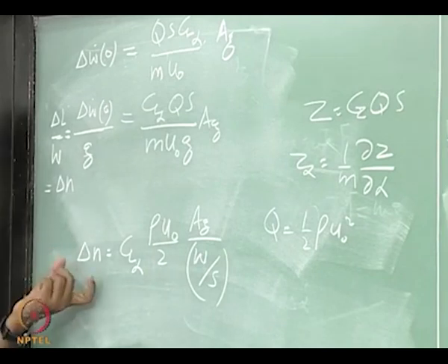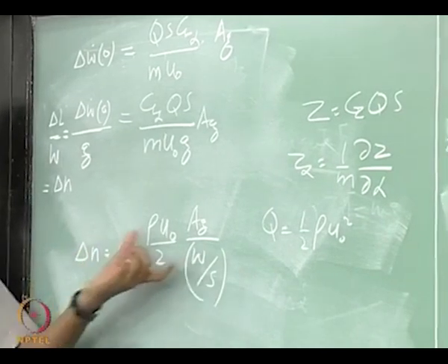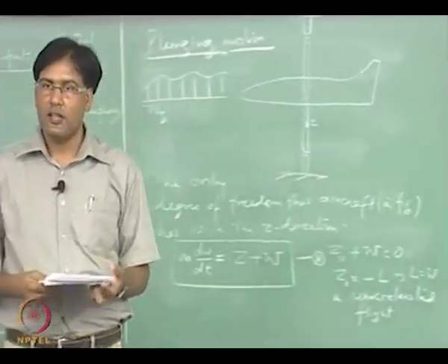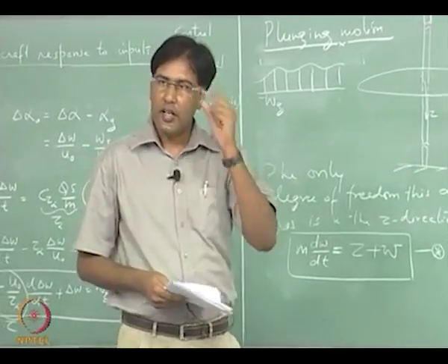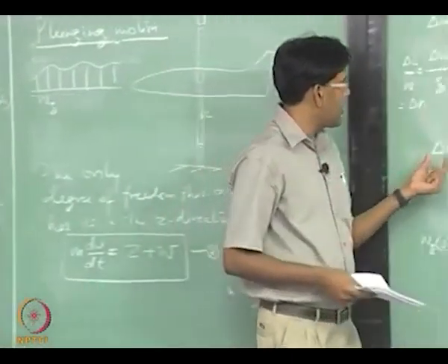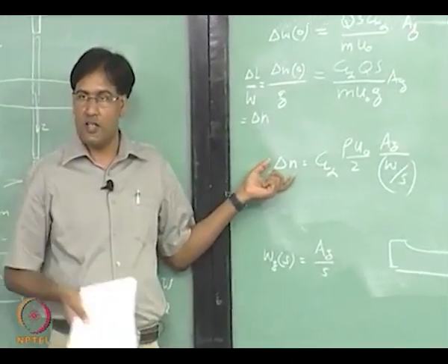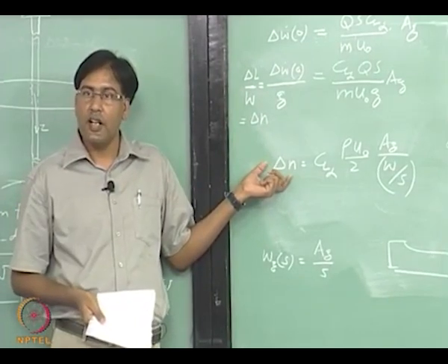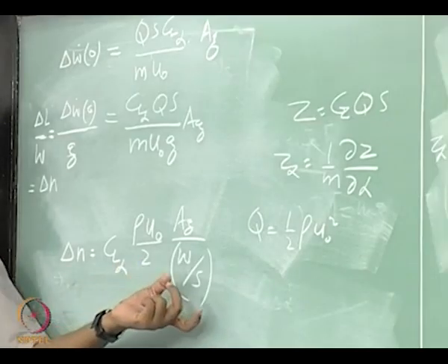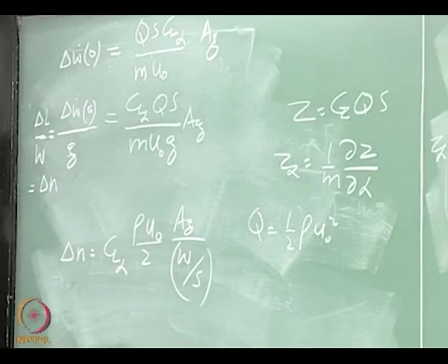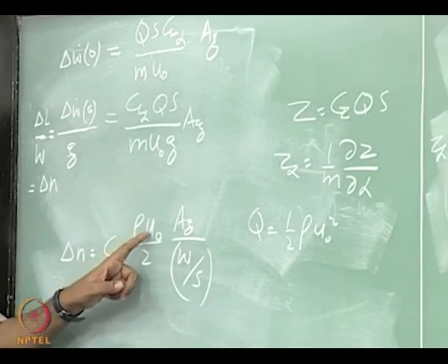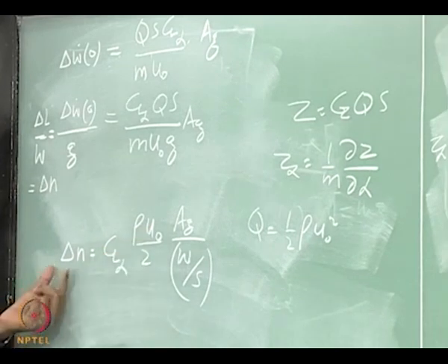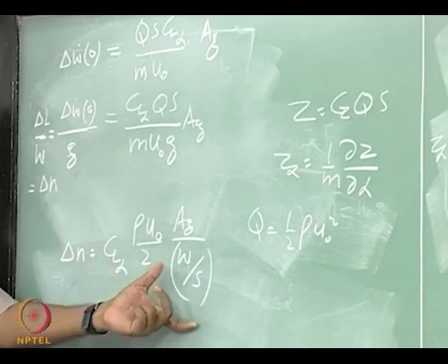So, this acceleration is definitely, from this formula you can see, going to depend upon how your wing loading is, right. High wing loading means low acceleration because of the vertical gust, right. Low wing loading, high acceleration at any particular speed. This is the equilibrium speed, right, forward velocity. It is going to depend upon what the wing loading is.